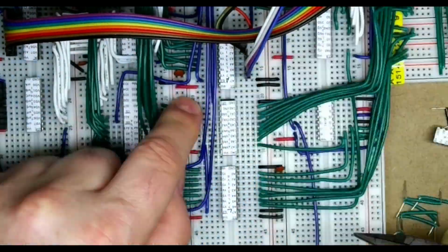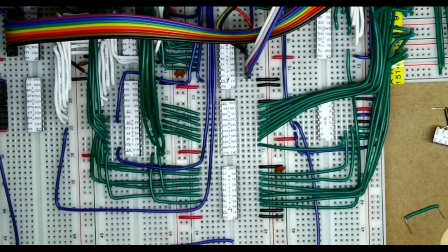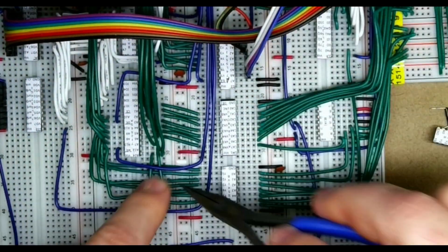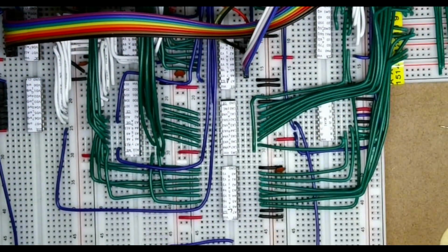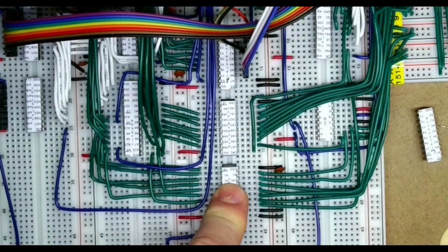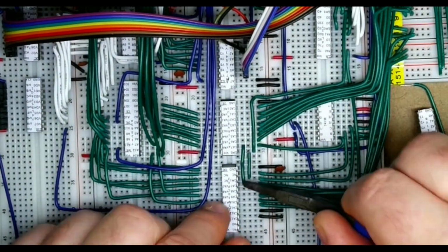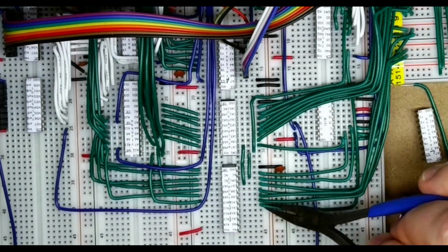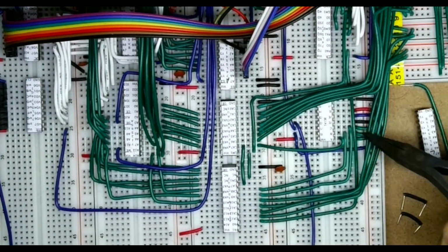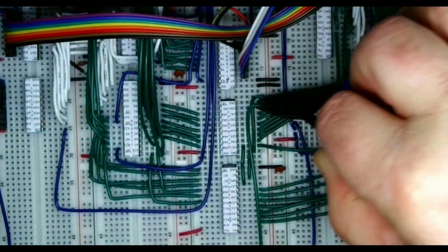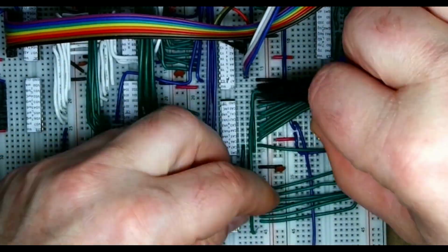Now in fact the left-hand address lines there need to move down one for the video address output, so just change those. Now we need to make sure we've got the graphics mode 1, and we'll also be putting the graphics mode 1 to go down from the second to the second chip, and also address line 7 as well. We're moving down the other address lines to line up, and then we need to put in the page address 0 and page address 1 into there as well.